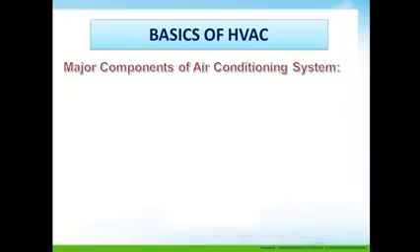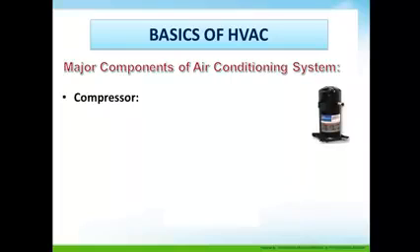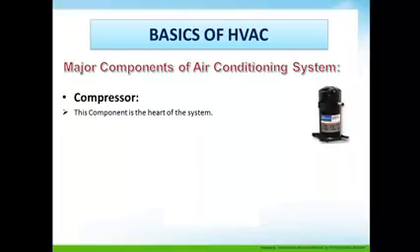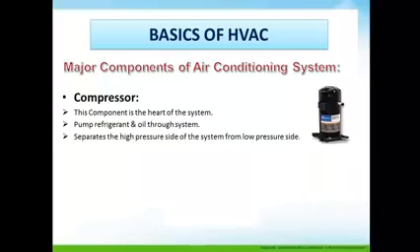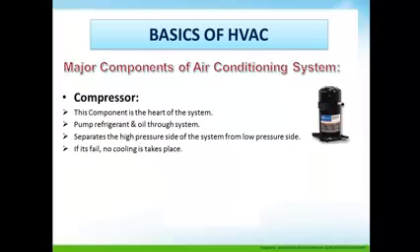Major components of air conditioning: compressor. This component is the heart of the system. It pumps refrigerant and oil through the system. It separates the high pressure side from the low pressure side of the system. If it fails, no cooling takes place.